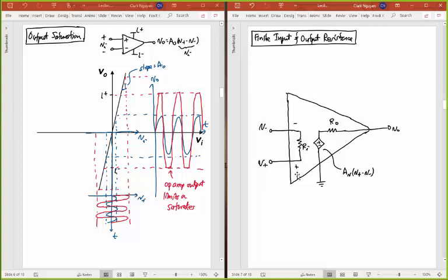And I should also say that, you know, if I really want to make this a non-ideal op-amp, you know that its actual transfer function is going to look like this. So if this is log omega, and this is A sub v of j omega, then this is going to look like this. Now you already know that the transfer function looks like this, and you already know that it's going to start going down at 20 dB per decade, starting at radian frequency omega b. You know that its gain is going to be whatever the gain was that we said it was before, A naught there. So you know that's its transfer function here.